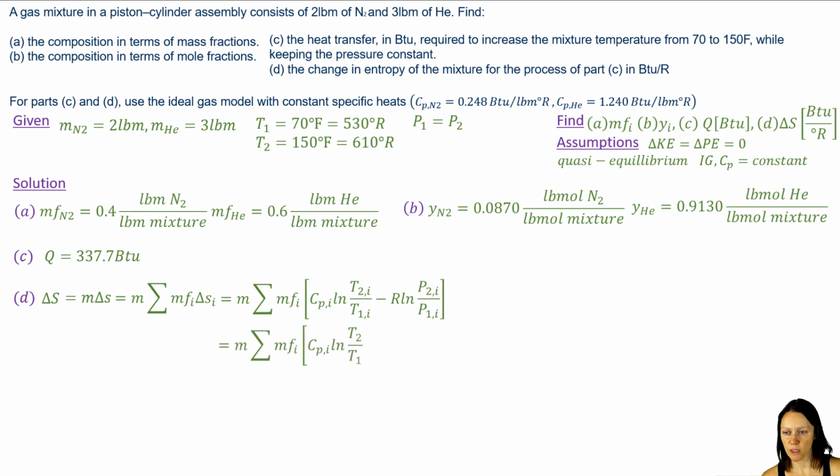So, all right, let's start looking at each of these components. First thing I'm going to do is drop the subscript i from the temperature, because once again I'm using Dalton's model, which says the temperature of the component and the mixture are the same. Now let's look at that pressure. I don't know anything about the component pressure, or I'm not given that information. However, I do know that by combining the ideal gas law and Dalton's model, I can put that partial pressure for each of the components at state 1 and state 2 in terms of the mole fraction at state 1 and state 2.